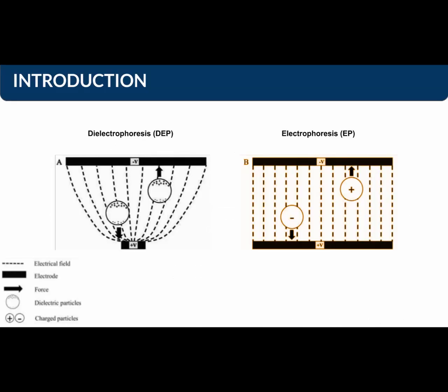Material characterization, as the name implies, is the process by which key characteristics of any given material are found and registered. Similarly, when the characteristics of a range of materials are well documented, characterization tools can be used to determine the material being tested. Dielectrophoresis is one of these tools, and it is the process by which small polarizable particles, usually at the micro or nanoscale, are subjected to an electric field, which induces an electrokinetic force which accelerates them in the direction of this field.